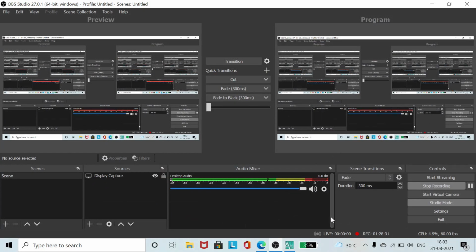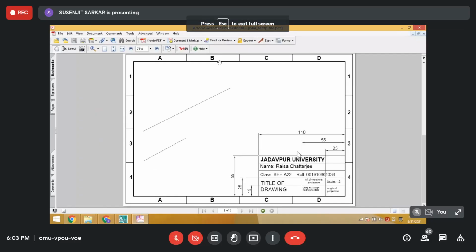We have completed so far the margin line, outside margin line, outer lines, inner lines with different thickness. We have divided the rectangle by exploding. We are separating the sides of the rectangle by the explode command. We have divided the lines by the divide command.